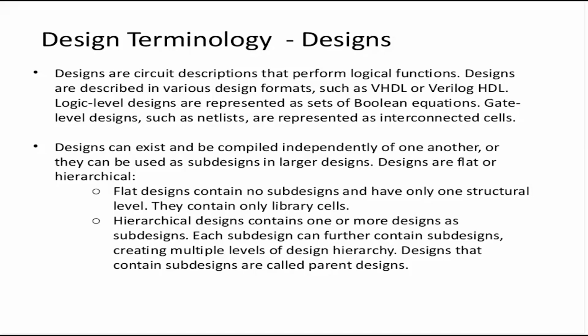A design, let's say an 8-bit microprocessor, can be represented in Verilog RTL. After synthesis, we'll get the gate level netlist, so it can also be represented in netlist format as interconnected cells. So a design is a CPU, but the representation depends on your usage. If you want to use it for RTL simulation, you have to use the Verilog design. If you want to use it for timing analysis, you have to use the netlist format.